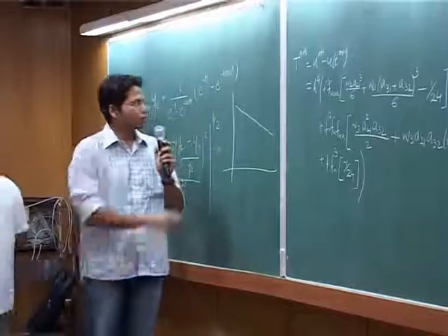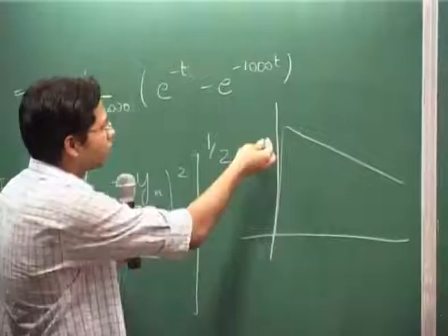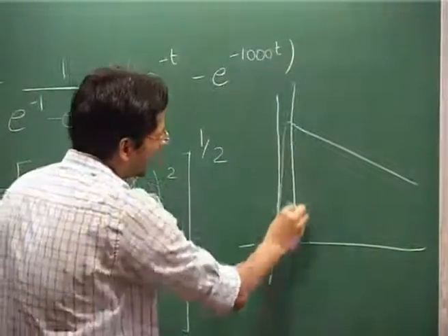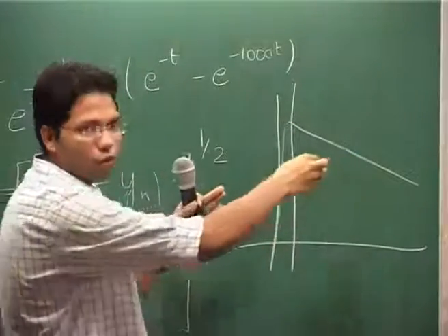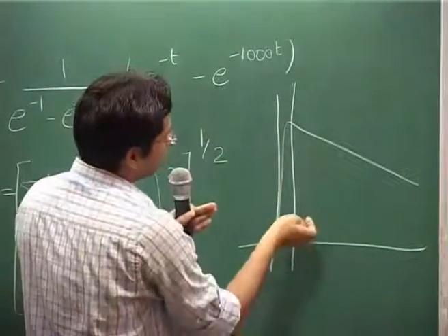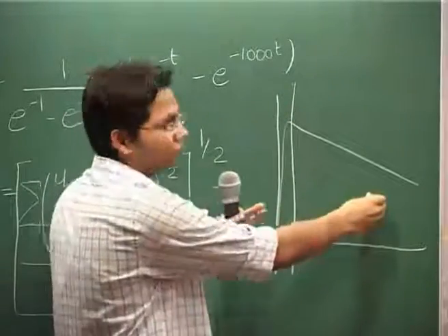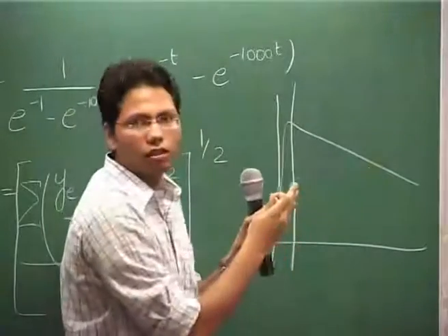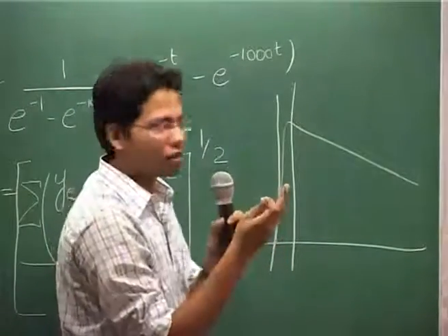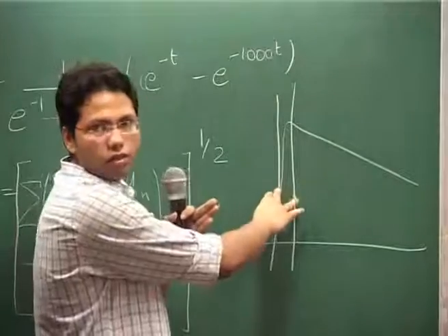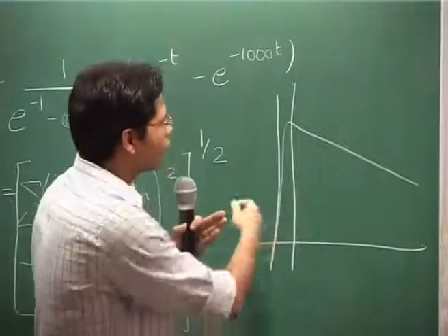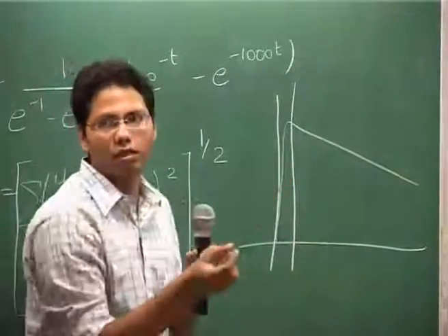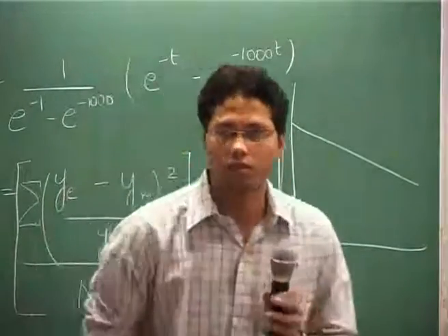So if we consider this is the form of solution which we are getting, this is quite like a boundary value problem. What we are talking about is if we divide this whole graph into two parts, we can have a different grid system for this domain and a different grid system for that domain. Since the change is quite gradual here, the grid spacing need not be as refined as for this case. So we can have a non-uniform grid system to solve this problem. That could be much faster than having a uniform, refined grid spacing for the entire range.